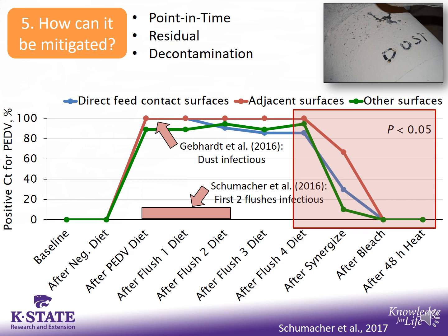We have tried to clean our biosafety level 2 feed mill just with physical cleaning methods, meaning that we are running through flushing or sequencing, or we are physically cleaning by removing all organic material and all dust that we can through air wands or compressed air. In this case, all that the air does and physical cleaning does is serve to actually increase the overall contamination rate as it spreads virus even more effectively throughout the mill.